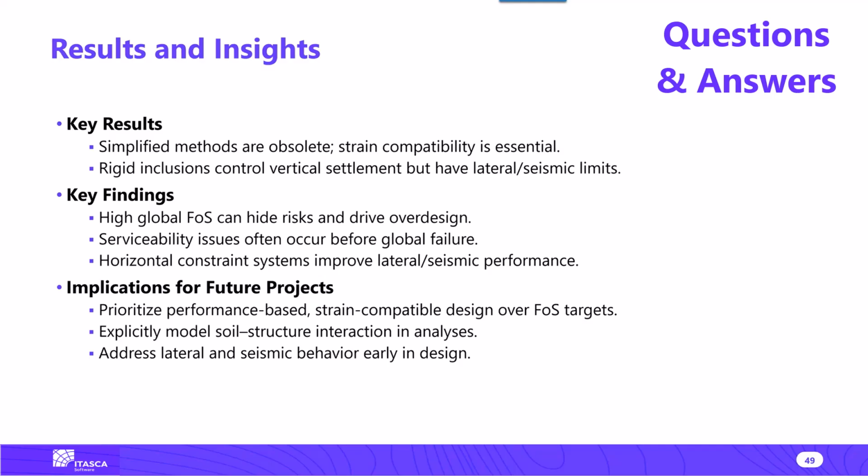The liner needs to be a separation. So you cannot just randomly put a liner, because otherwise you would not be able to capture, let's say, relative movement. If you have a liner, like for example a D-wall, a diaphragm wall for an excavation, you're creating a cut in the soil. So that is a liner. You cannot model that with shell because you cannot generate a different separation. So in that case, it's just much simpler to use the faces to generate the structural element itself.